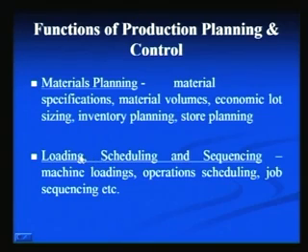Loading is basically the assignment of work to equipment or resources. In this case we have to prepare a load chart. For example, say 5 jobs are assigned to a machine or to a worker, then these jobs are represented in the form of a load chart. Say the 5 jobs are A, B, C, D, E. So, we will prepare the load chart of that worker or machine by assigning those jobs to that worker or machine. Scheduling is basically a time based loading.